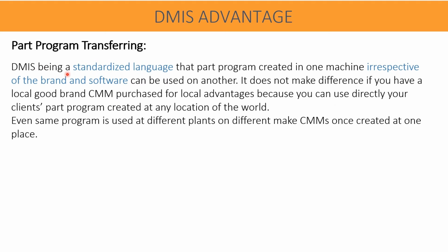There are various other advantages of using DMIS programs. Part program transferring: DMIS being a standard language, a part program created on one machine, irrespective of the brand and software, can be used on another machine.